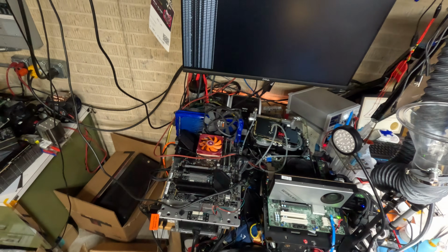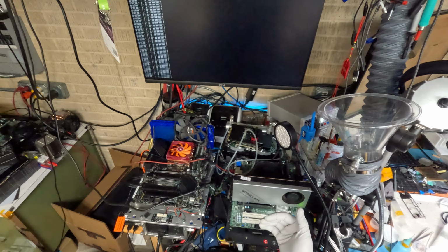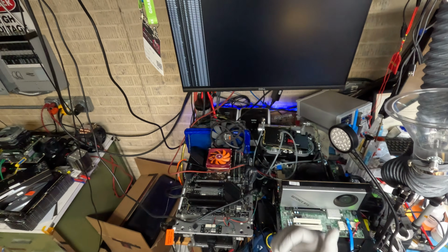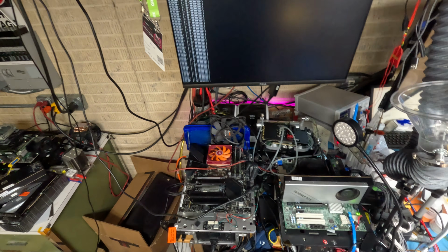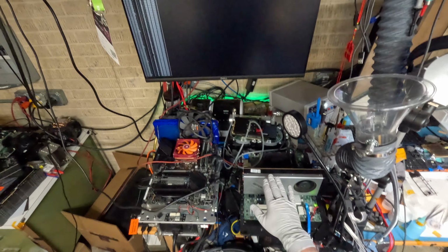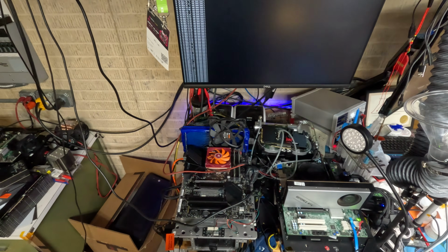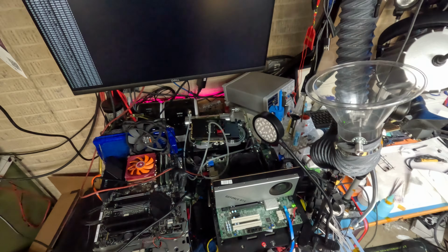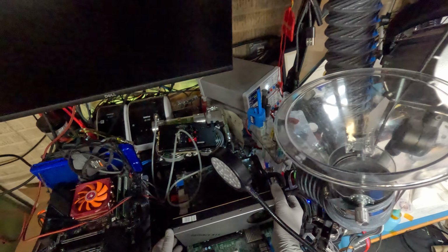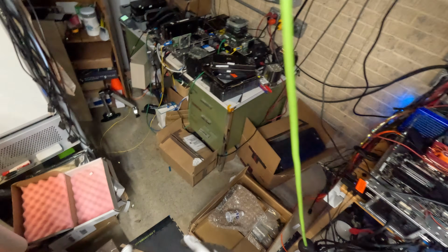So modules D0 and D1 were showing issues. I replaced both sides of those. NVMT doesn't tell you which side of the chip select is having issues, so you just have to replace both of them and then figure out what to do with them later. So now it doesn't show issues on NVMT, so you think, okay, great, everything's fine. Well, the reason I started this video is because it's actually showing issues, but not on NVMT. It's just crashing as a device on NVIDIA SMI.